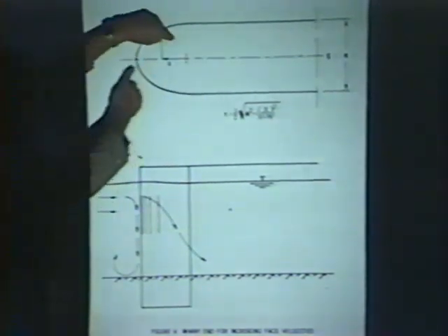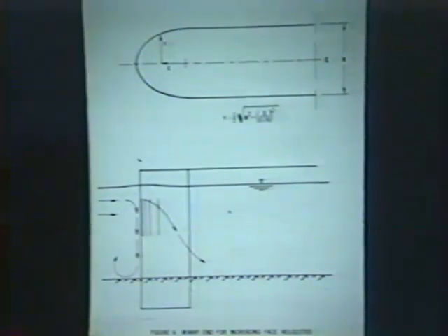Well, to summarize then, the points I want to leave you with are, first of all, know your estuary, generally. That's really important. And it's worth spending some time looking at hydrographic surveys over a period of time to see what the trends are, finding out what the sediment composition is, what the supply of sediment is to the system, and what the wind patterns are and the seasonal changes in freshwater outflows and winds and so forth.